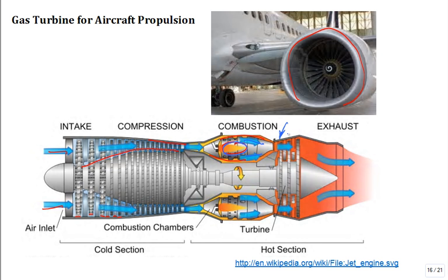But then they have some turbine stages. Usually they're on different shafts. Some of them feed the compressor. Before, you'd have different turbines, and they would feed the shaft to drive the electric generator. But here, there's no power needed. This is different than a stationary gas turbine.